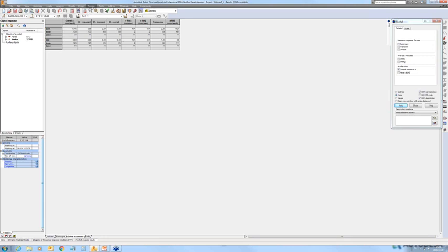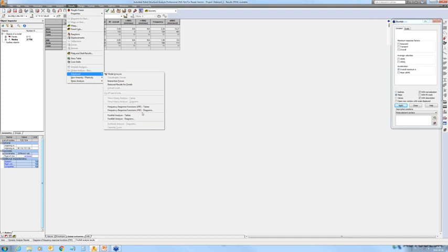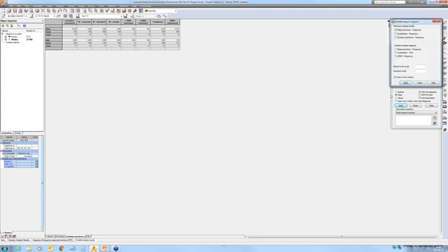So now if we go to the results in the graphical form, advanced, and we have footfall analysis diagrams, we may display the results for this very node, 133, and the excitation.